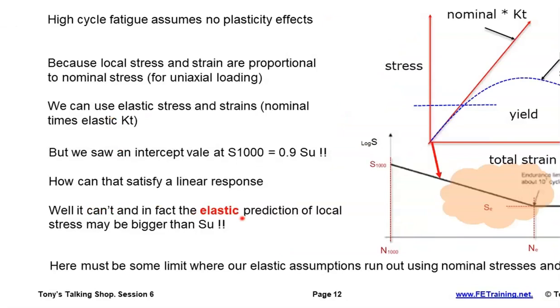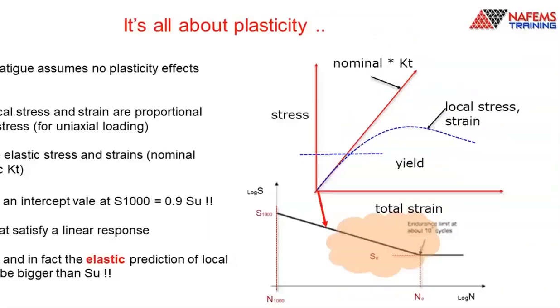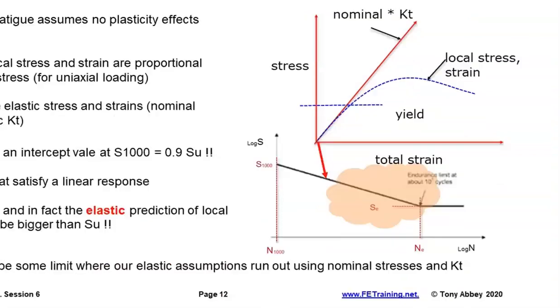What we're doing is, the real material is going to go up this pecked blue curve. If we run a linear analysis, as many of us have seen, if we just overshoot, we get into realms of ridiculous levels of stress. So nominal times stress concentration factor can take us up here, which is complete nonsense, and that cannot be fitting into any rationalized SN curve.